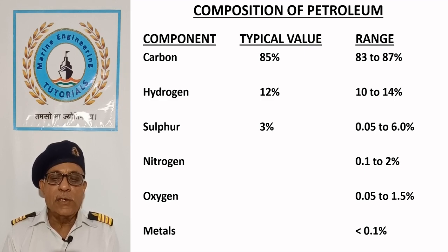Whenever high sulfur fuel oil with sulfur content more than 0.5% is used outside the emission control areas, ships should be equipped with an exhaust gas cleaning system. However, within emission control areas, the fuel in use should have sulfur content less than 0.1%.